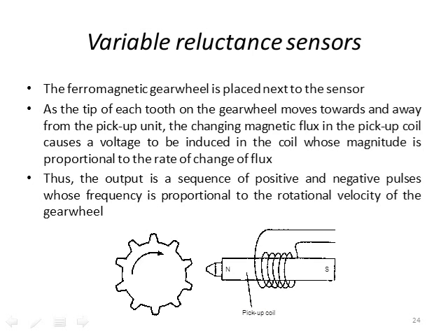rotating wheel, and as the air gap between the tooth of the wheel on the left-hand side is small with respect to the tooth on the pickup coil, then the reluctance is going to change a certain amount. Then when we're in the non-tooth region of the rotating wheel, you're going to get a variable signal, the induced current signal, or actually the voltage that you induce at the terminals of the coil is going to change respectively with the air gap changing, getting smaller, larger, smaller, larger.